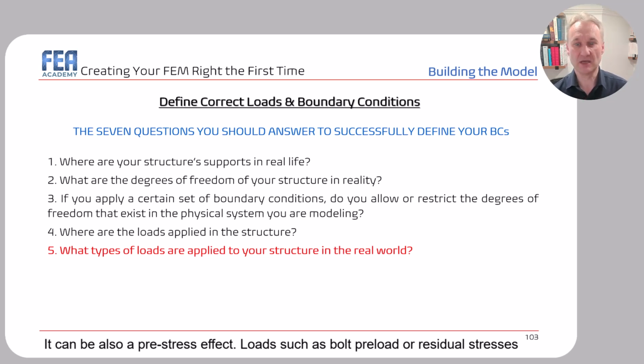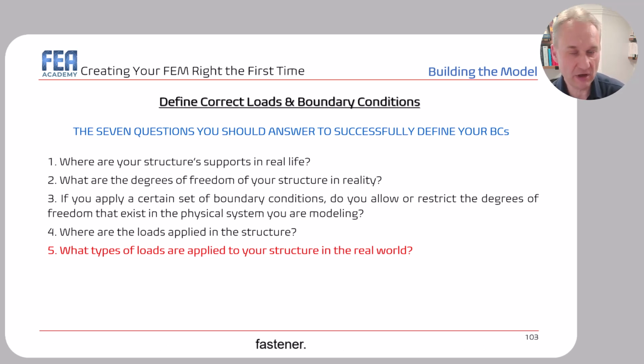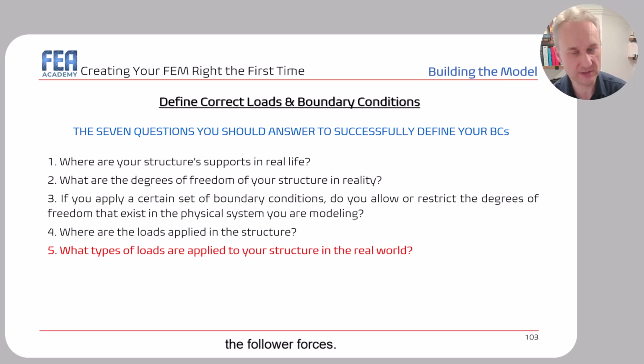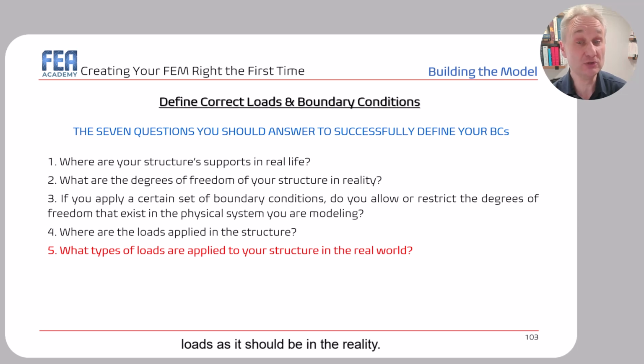Loads such as bolt preload or residual stresses from manufacturing, like welding, forging, or when you close a gap by tightening a fastener. You also have the nonlinear loads, loads that depend on deformation, such as follower forces. So ensure that the boundary conditions allow the structure to react to the applied loads as it would in reality.